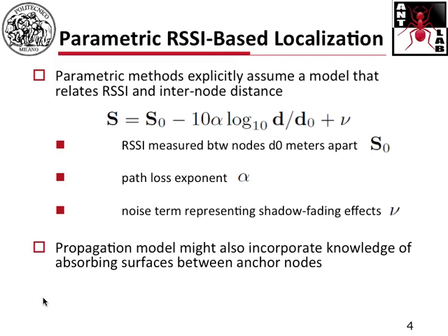Okay, and these models here are most likely exponential, which means that the received power decreases as a power law with respect to the distance. So the received power decreases with d to the minus alpha. The formula here is expressed in logarithmic form. That's why you just sum up things, you don't multiply.